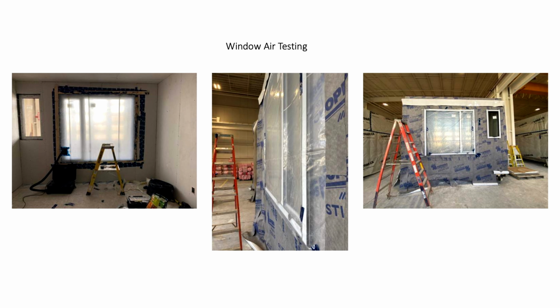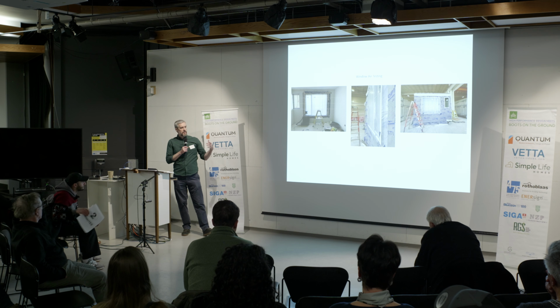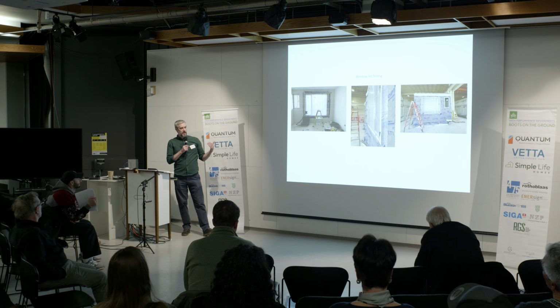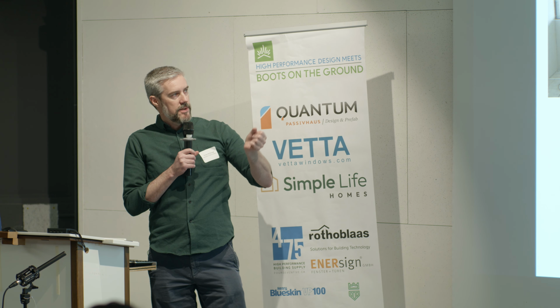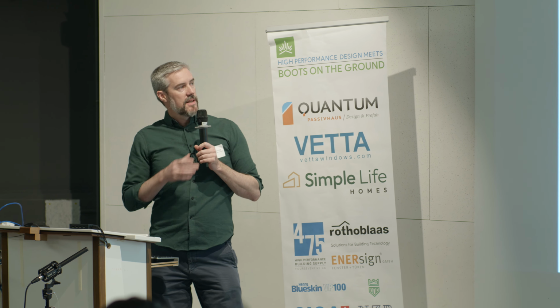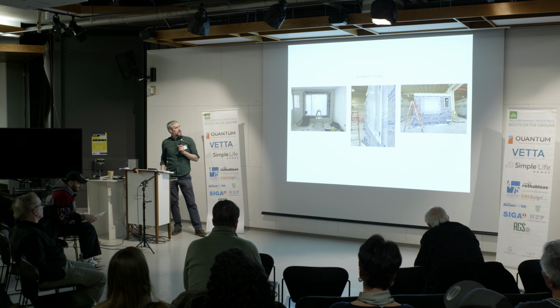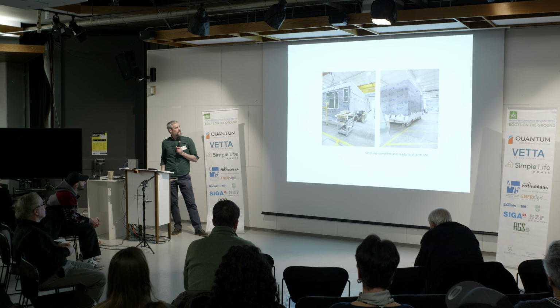The window testing itself: because the windows that we ordered did meet CSA A440, we were thrilled that we got these on site, but when we went to do our testing of the windows, they just kept failing, over and over, and we kept having to bring the manufacturer back to tweak the gaskets, tweak the hinges and up the pressure on it. We eventually passed them all, but we ended up doing tests on every single one of the windows. So that was a real headache that we overcame, but I think had we had more options for window manufacturers and more time, we might have asked more questions on that. So it was a big lesson for us.